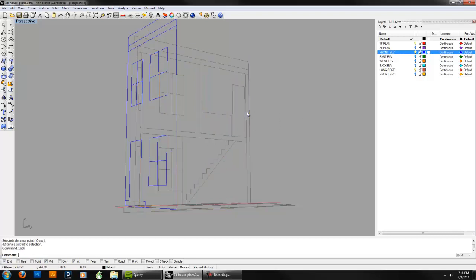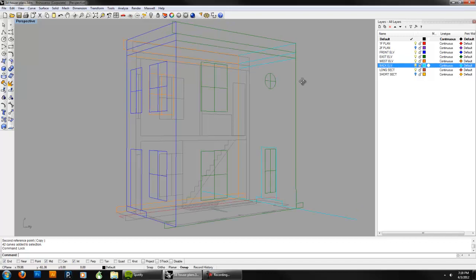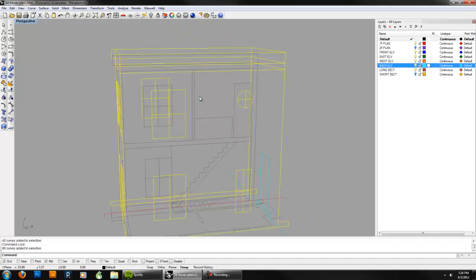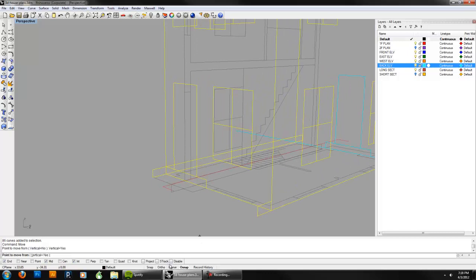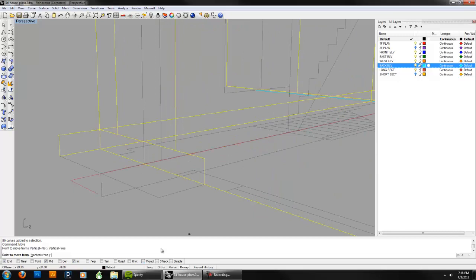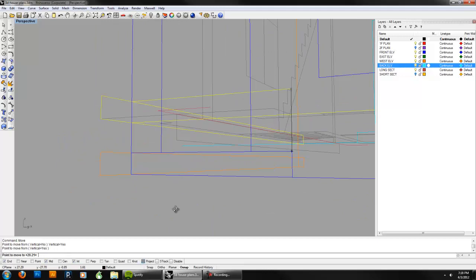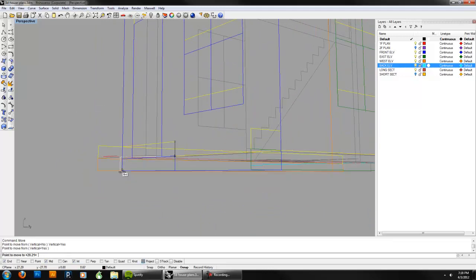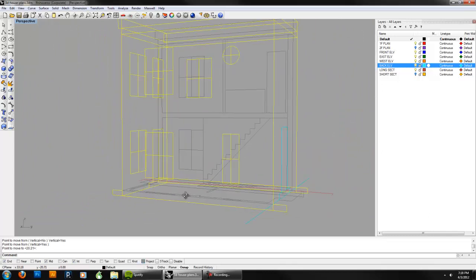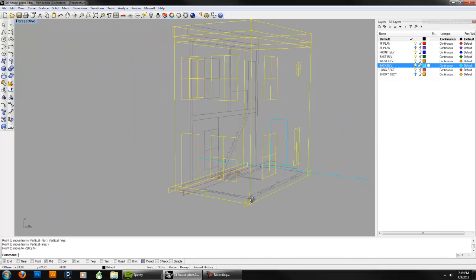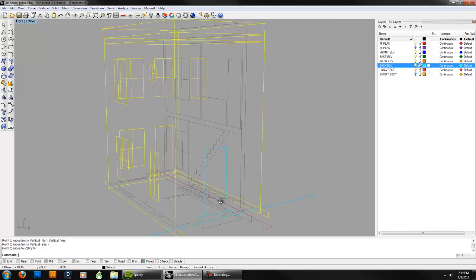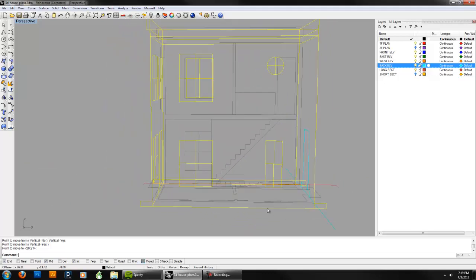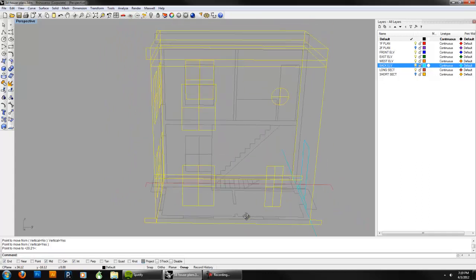So I'm going to go ahead and lock the section and turn on all my elevations and select them, and then say move vertical, yes, check that, and basically using the project snap, I'm going to go ahead and pick a location here, and using project, I'm just going to snap it to the bottom of the section, and that's going to line everything up. So that's helpful. Okay, so that's a mistake that I made. But there's kind of a level on the base of it that connects with these entry pieces here, and that's where the floor actually starts. Okay, so be really careful with your drawings.